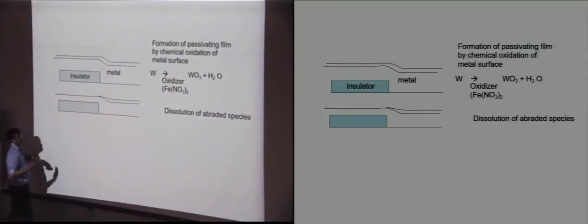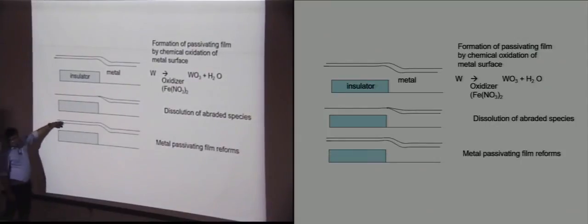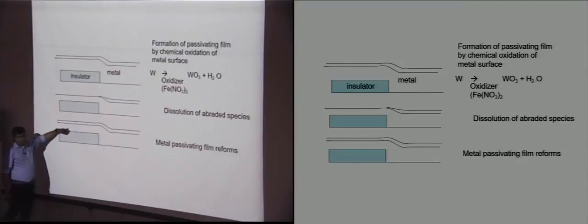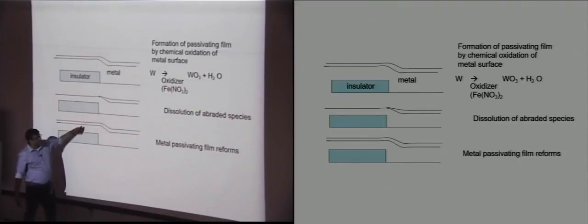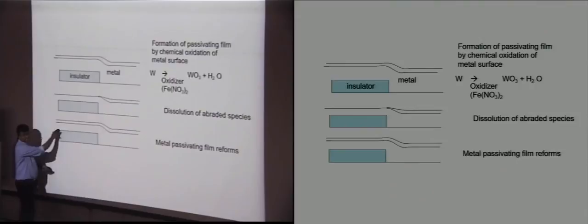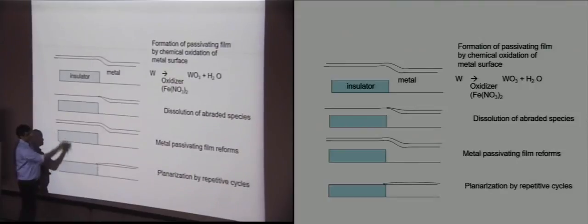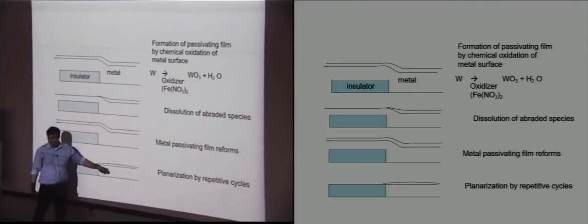But the moment it starts to attack, it will again oxidize. So again this slows down. Again, because the pad is touching this part preferentially, the pad and the slurry remove this tungsten oxide, again allowing a bit of the etching to happen. And so on and so forth, it continues to happen until the film becomes flat.